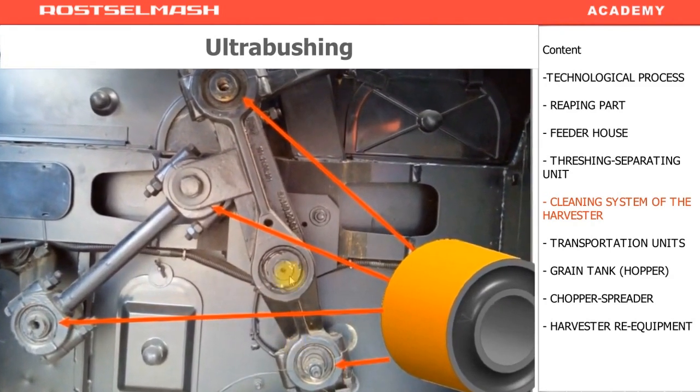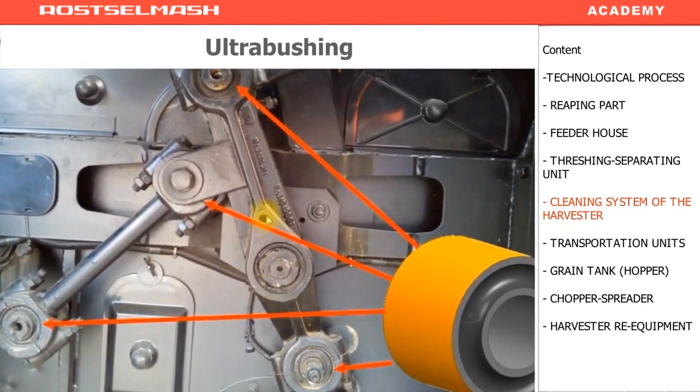To put the tiller in the neutral position, you have to install the pin that will go through the tiller and then go through one of the holes. On this platform we have got two holes. One hole is visible, while the other one is not because it is located behind the tiller. Insert the pin into the hole which is not visible.